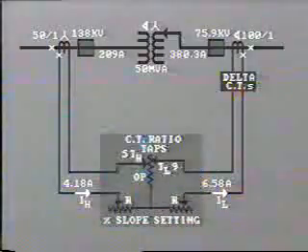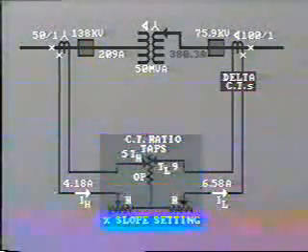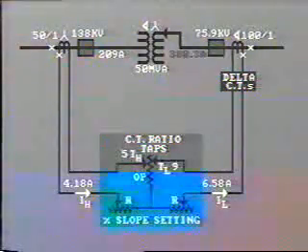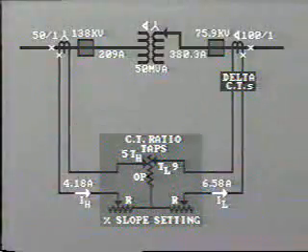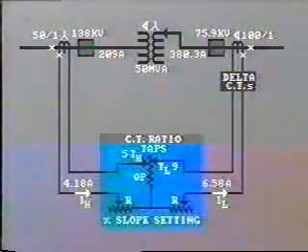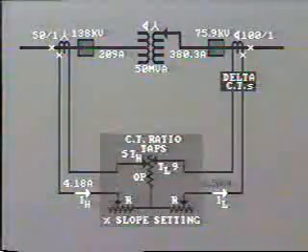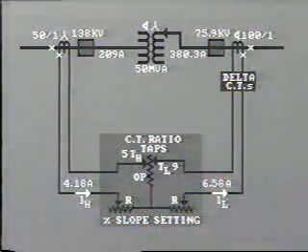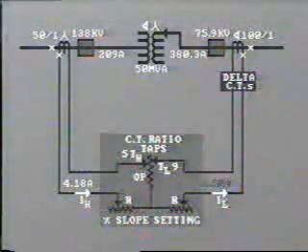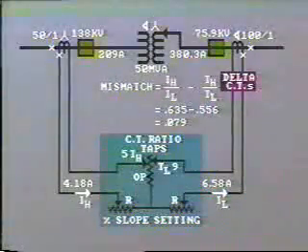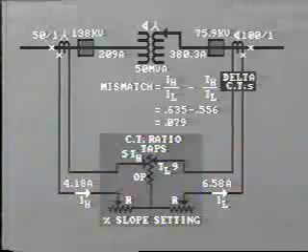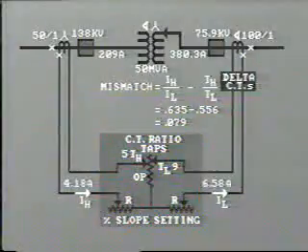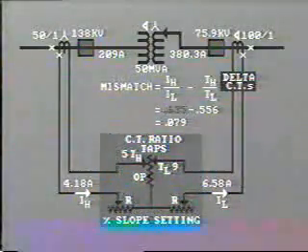Line current in the secondary would now be 50,000 divided by root 3 times 75.9, which equals 380.3 amps. The secondary current in the restraint winding would now be 380.3 divided by 100 times root 3, or 6.58 amps. So the ratio IH to IL is now 4.18 as before, divided by 6.58, which equals 0.635.